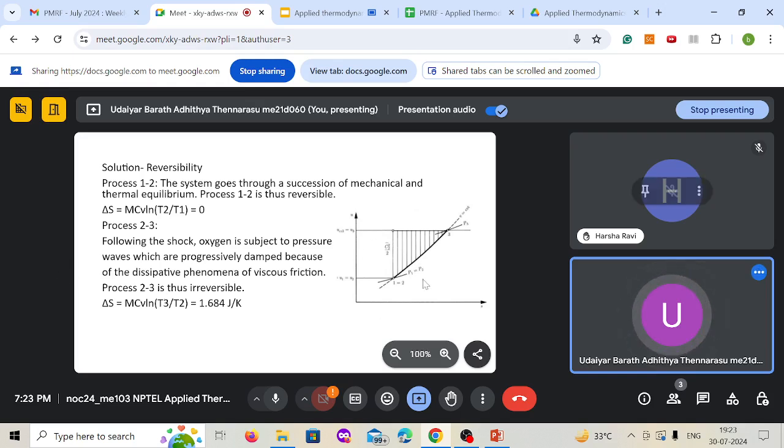Here on the right is a plot showing how the process is happening, plotted as internal energy versus entropy. From 1 to 2, there is no internal energy change. Your oxygen is at U1, so there is no change in internal energy of the oxygen. U1 and U2, the oxygen is at the same internal energy, but the vessel, the total system, is at higher energy U3. That is because of the kinetic energy possessed by the vessel. So U3 is the total energy of the system.